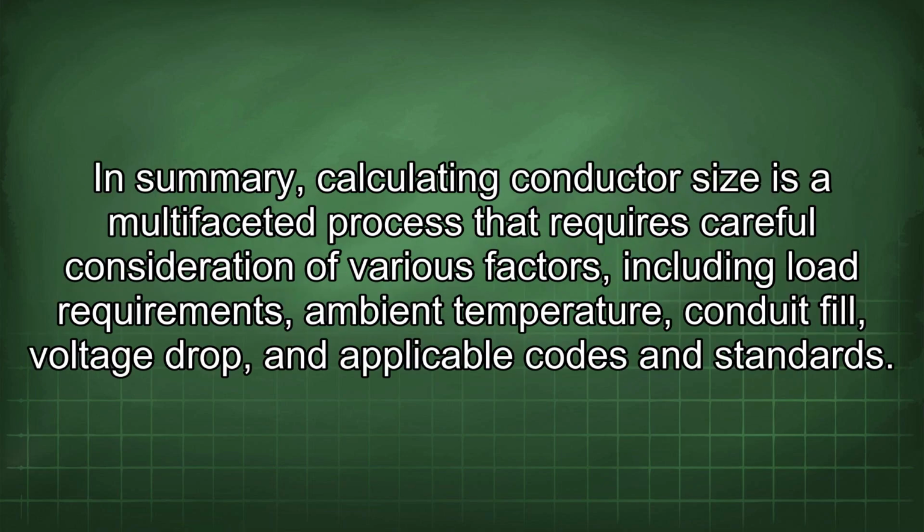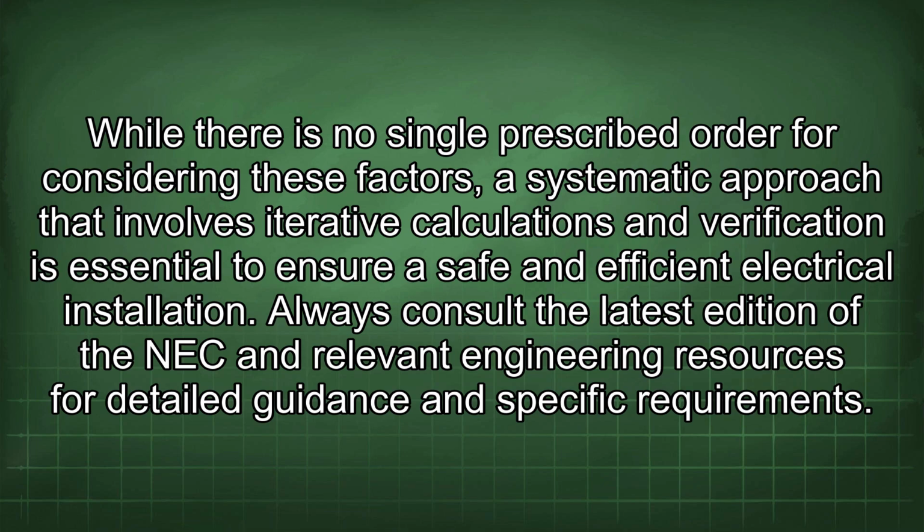In summary, calculating conductor size is a multifaceted process that requires careful consideration of various factors, including load requirements, ambient temperature, conduit fill, voltage drop, and applicable codes and standards. While there is no single prescribed order for considering these factors, a systematic approach that involves iterative calculations and verification is essential to ensure a safe and efficient electrical installation.